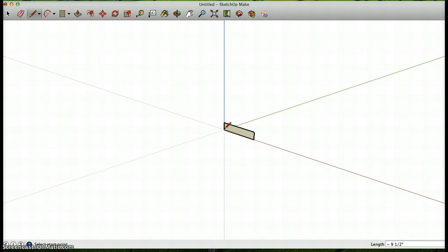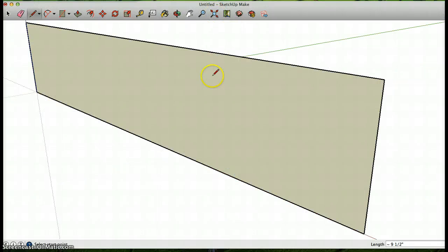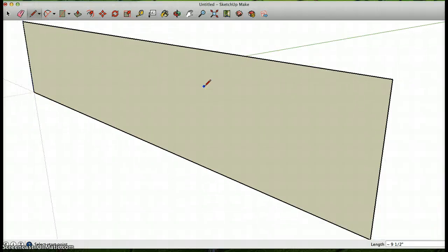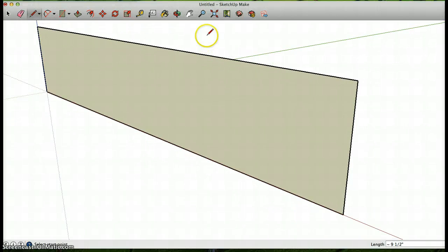So I'm going to draw that out. Okay? Anytime you just want to get out of whatever you're doing, you just need out. Just click escape. Alright? And then this button, zoom extents, that's just going to zoom me into the full screen of what I've just drawn. Two-finger scroll zooms in and out.